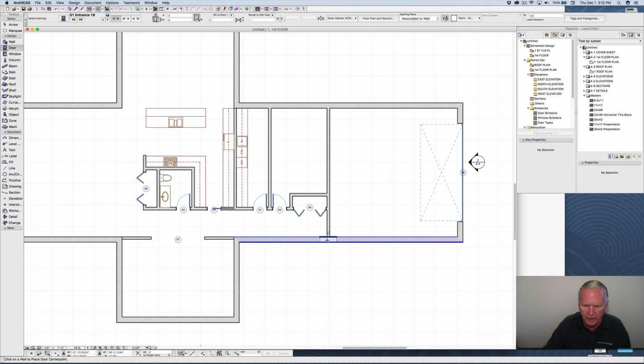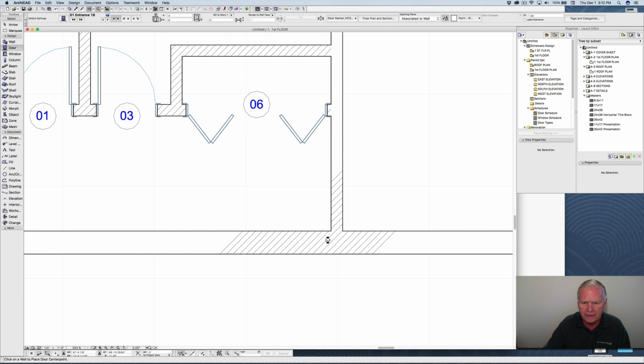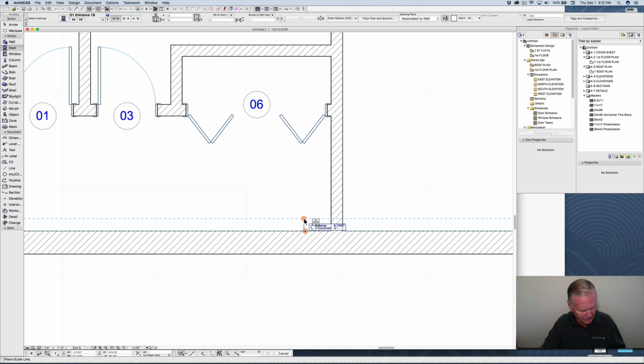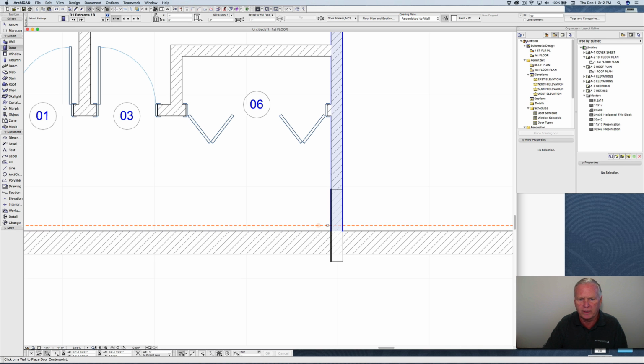All right, there we go. So we want to put that in 3 inches from that wall. So we'll hover, we'll get that guideline, drag it up, D, 3 inches, and that's where we're going to put in our door. Now we're in the center insertion, so we have to go up here and go to the other. We'll see if I caught the right one. I didn't. It's the other. You know, for as long as I've used this program, it just baffles me as to the logic there. We should probably spend a few minutes thinking about that.